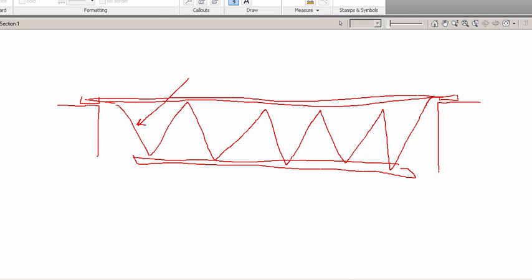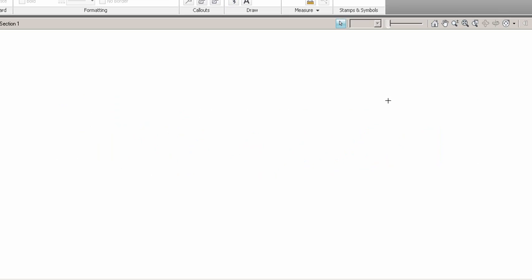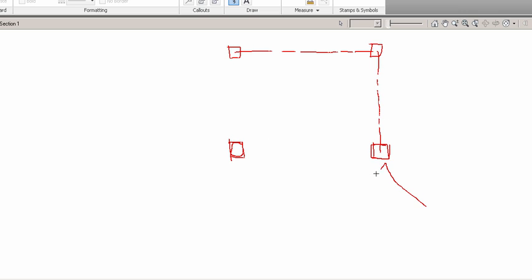So, on a set of plans, sorry, I'm throwing too much information at you at once. On a set of plans, you might see a steel drawing. Let's say here's a column, and this would be in like a blueprint of a building plan, like a floor plan, if you will. And you might see something like this, where you see a line going this way and a center line going this way, and you're going to see some kind of little block or circle, and you're in a plan view. So this is a floor plan of a building. This, of course, would be a column coming out of the page at you, coming up. And this might be the beam.